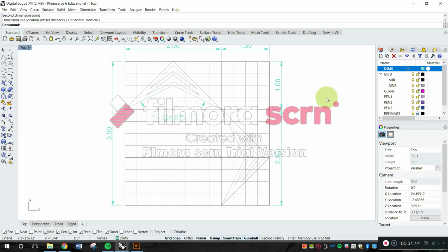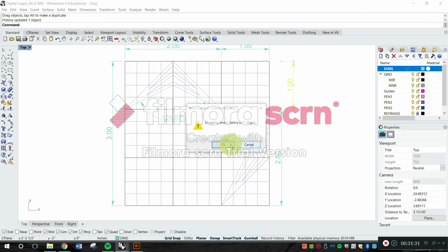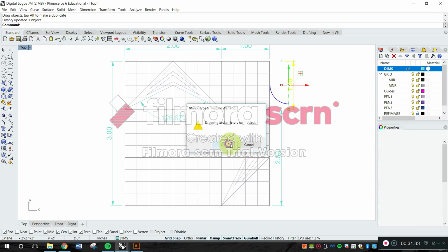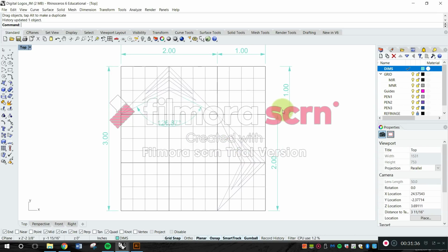Now, dimensioning drawings has specific standard rules when you're doing architectural drawings. One of the basic ones is that your dimension strings should be aligned when they're continuous. What do I mean? When you have that, for example, and by the way, you get that message, I'm going to say okay for right now. That's not ideal. If we know that this number and this number add up to this equal length right here, they should actually be together like that.